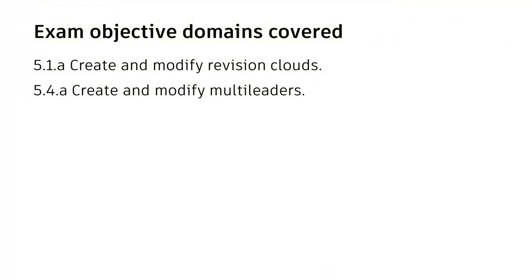In this lesson, you learned how to place a revision cloud using different options. We modified the RevCloud appearance using the arc length option. We used the Modify option to change the RevCloud boundary. We used the multileader command to place a revision tag, and we used properties to change the scale of the multileader.